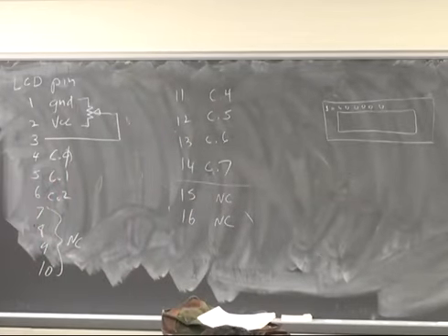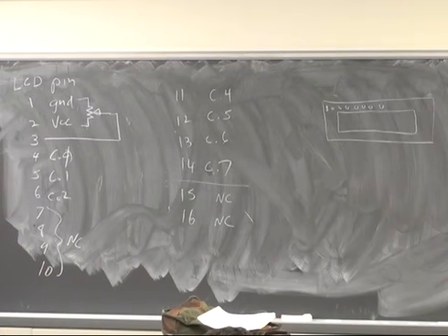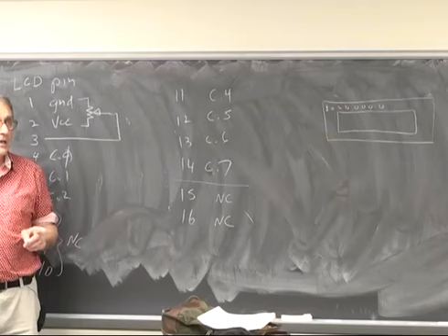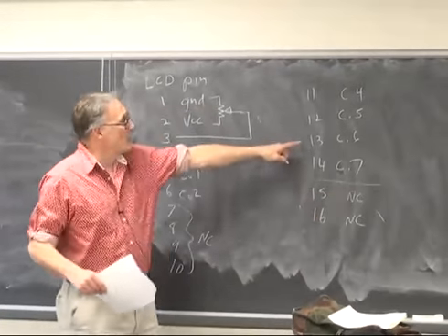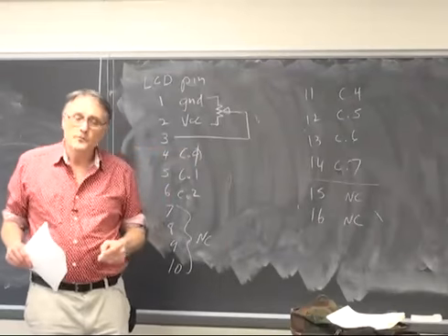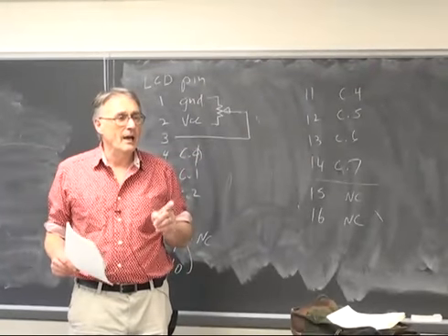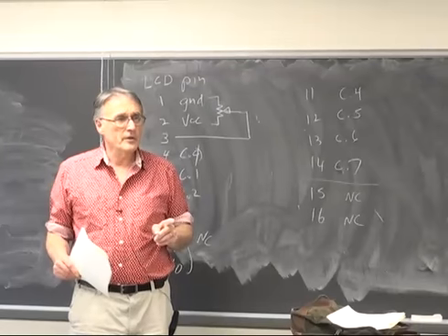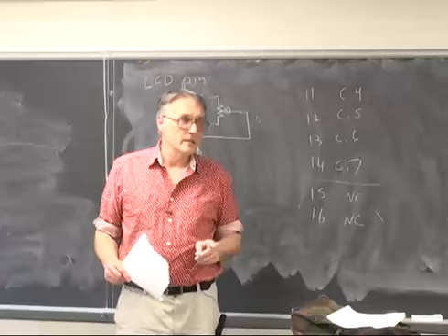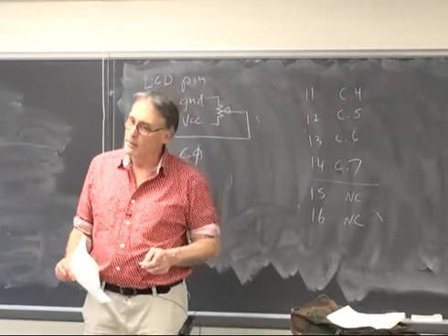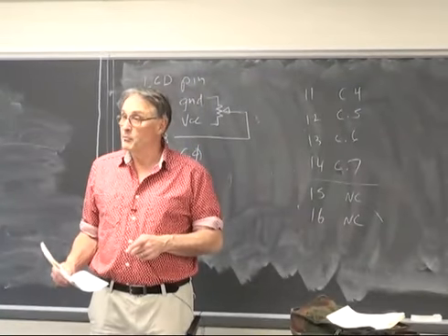You can use any port you want, except don't use port B. The reason for not using port B is that the CPU is programmed through port B, actually B.5, 6, and 7, which happens to be the data bus. So if you happen to interrupt the operation of the LCD during a read operation, then the LCD will be driving the bus, and the programmer cannot program the chip. And you'll get a program failure.